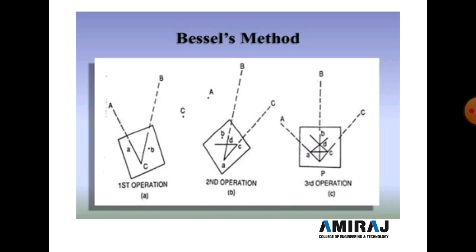Then the lines to capital A, small a, capital B, small b, and capital C, small c are drawn. These three rays intersect at some point, the P point, which is marked on the paper as small p, and by using the U-fork and plumb bob we easily transfer it from the paper to the ground and mark this point with a wooden peg.